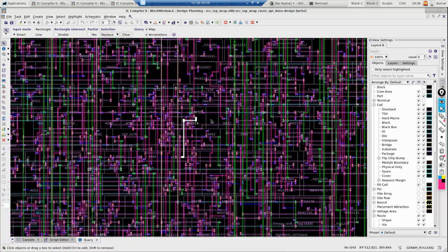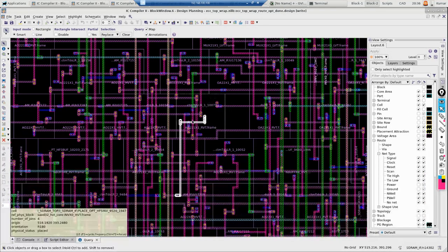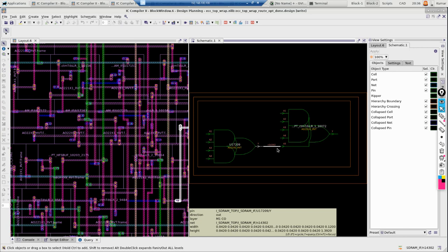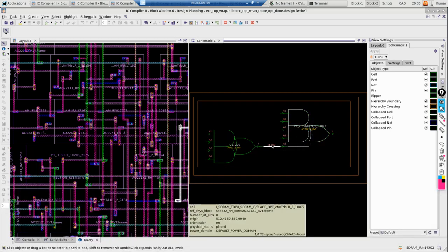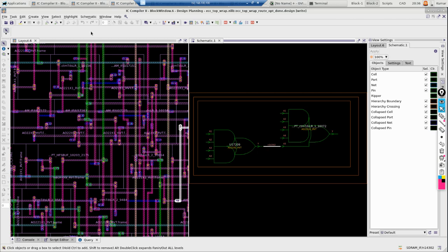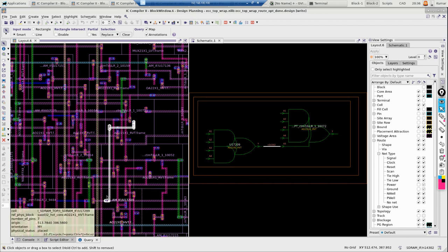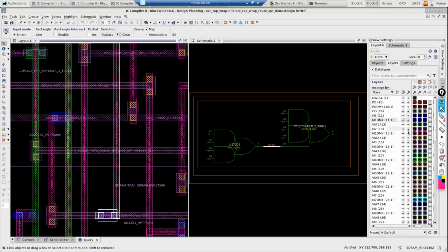Now if you look at this particular thing, say this is your circuit. This is your net that is connecting this cell. There is an output which is going to an input, which is an AOI cell. This is the net, that's a logical net. Now, how is that logical net routed? Look at here. We have used the actual layers. We have different layers: M1 layer, M2 layer, via, M3, M4, M5, and all these layers.